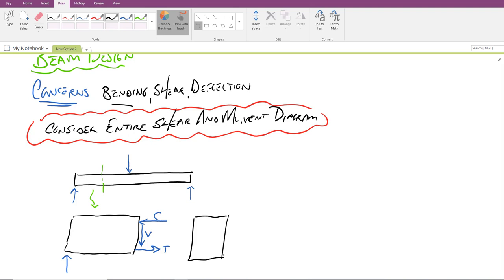It could actually be right where we've cut it, and we've turned it sideways now so we can see inside. We'll note that there's some sort of a neutral axis acting along, typically around the center of the member, and everything along this top edge will be in compression, and everything along the bottom will be in tension.